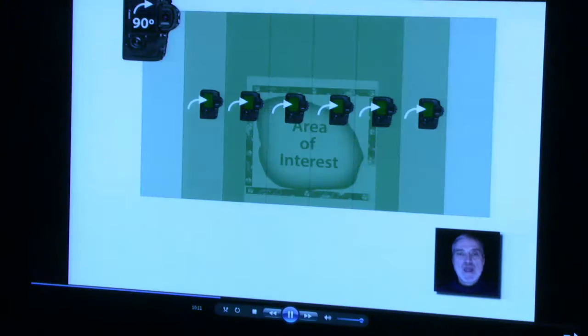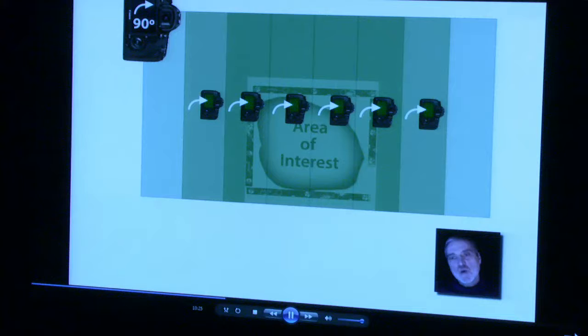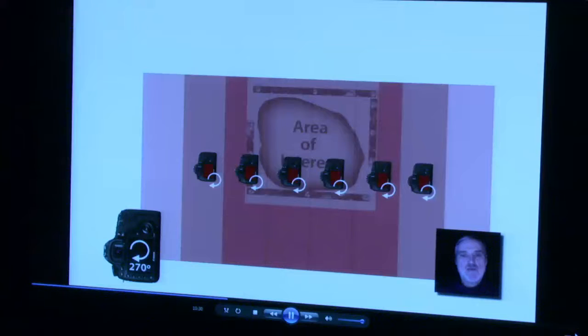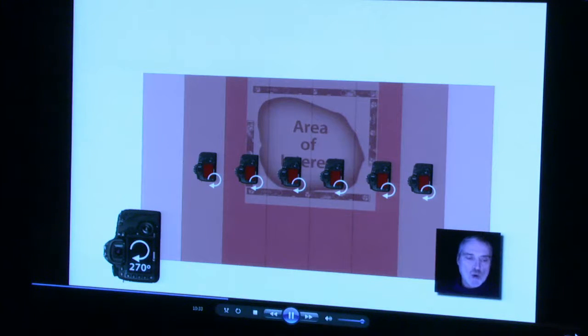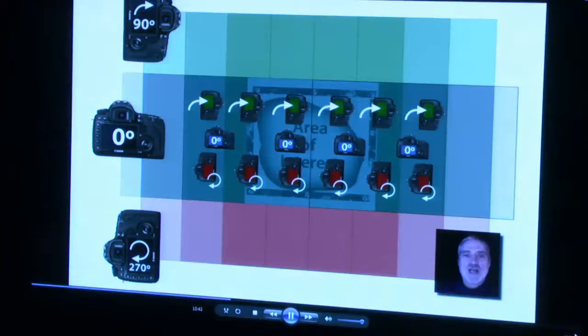What we do now is take the camera, move it up slightly, tilt it down about 15 degrees, and rotate the camera 90 degrees to portrait mode, then do 2/3 overlapping shots covering the area of interest as we have described. Then you take the camera, lower it below your first strip of images, tilt it up 15 degrees, and repeat the 2/3 overlap process. So what this gives you is 9 look angles at each point on your surface.